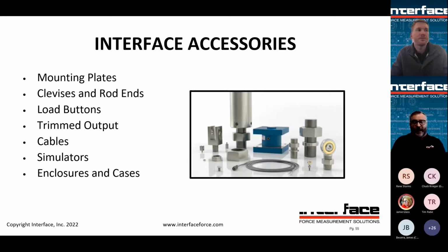Again, we offer trimmed output, which is matching the load cells to have the same output. Different cable lengths and long cable runs and things we can accommodate. Millivolt per volt simulators are very useful. Basically dial in a millivolt per volt value, and that's the same as putting a load on the load cell. So you can use something like that to dial through some loads when you're setting up a display. Very useful for troubleshooting too.